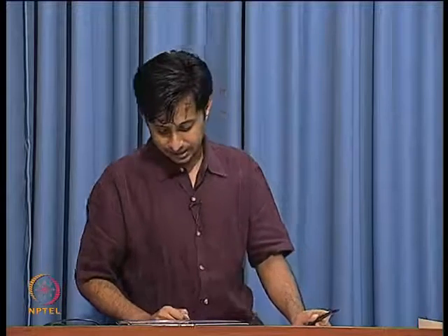All right. So, this is the basic stuff. Now, when we are talking about the antenna, it is something like a waveguide that has a characteristic impedance. The antenna hands over the signal to the atmosphere, which also has similar properties. Then the atmosphere hands over the signal to another antenna, which is also a waveguide, and that antenna finally hands over the signal to the low noise amplifier.